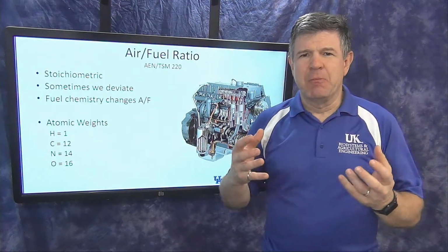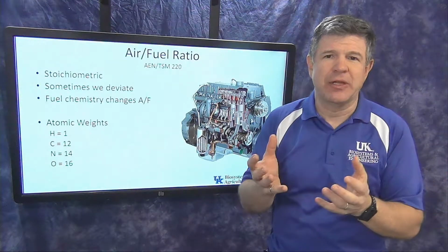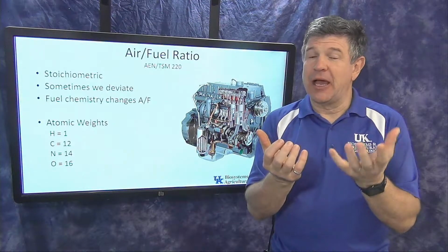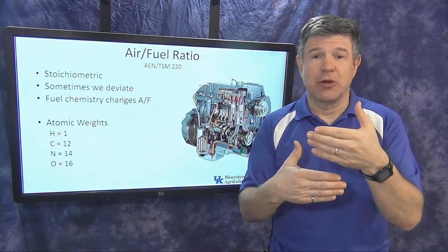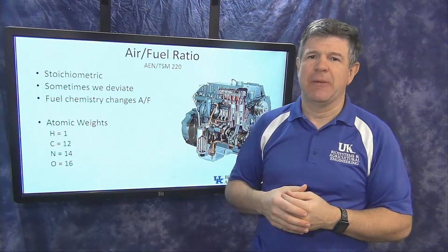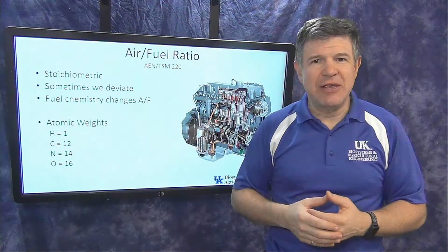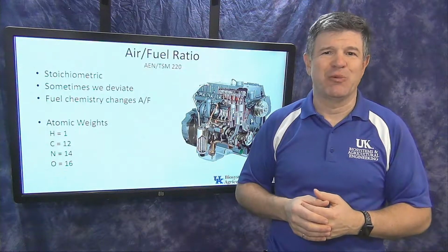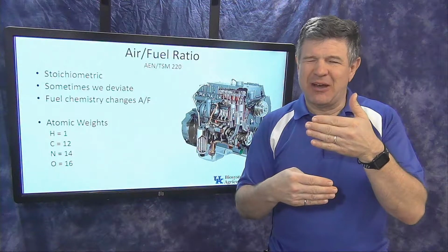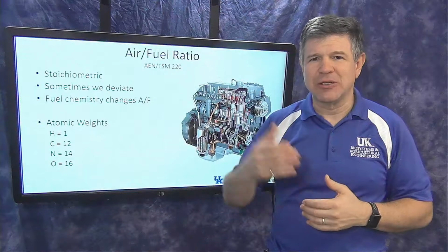So that is based on that chemistry equation that we just balanced for the fuel and the air. We're going to calculate ideally and theoretically how much air should go with a certain amount of fuel that's going to that engine. Give us an idea what that air-fuel ratio should be. Now, what you'll find out in practice is that pretty often we deviate from that a little bit. So that air-fuel ratio is not really perfectly at that stoichiometric ratio. It's going to be off a little bit.